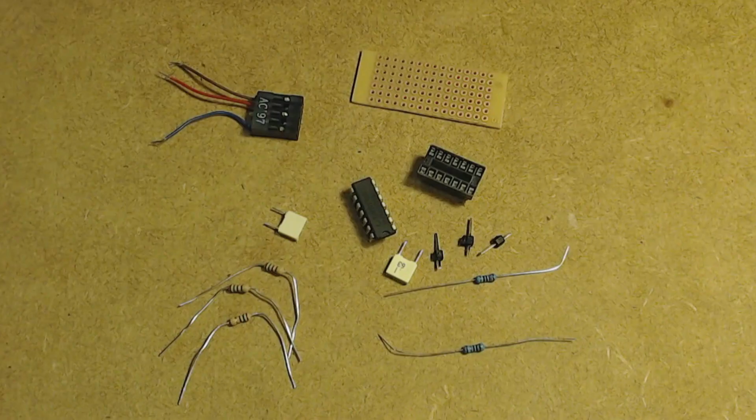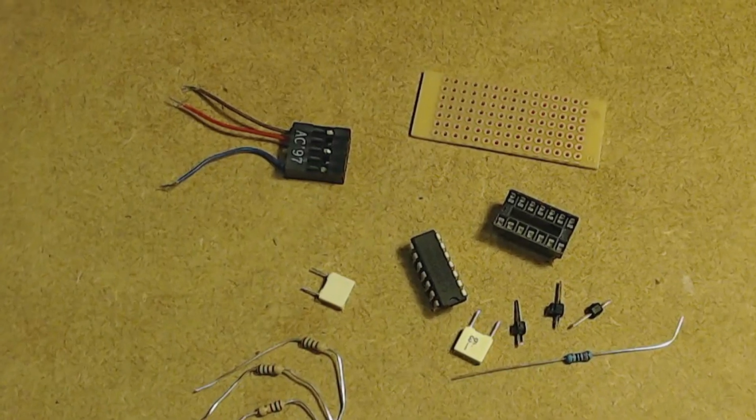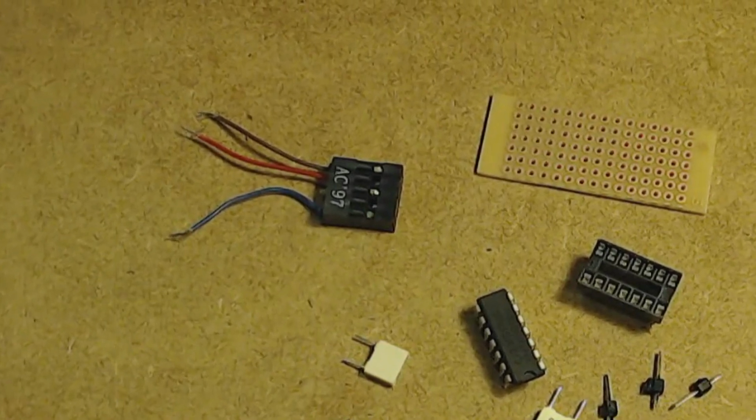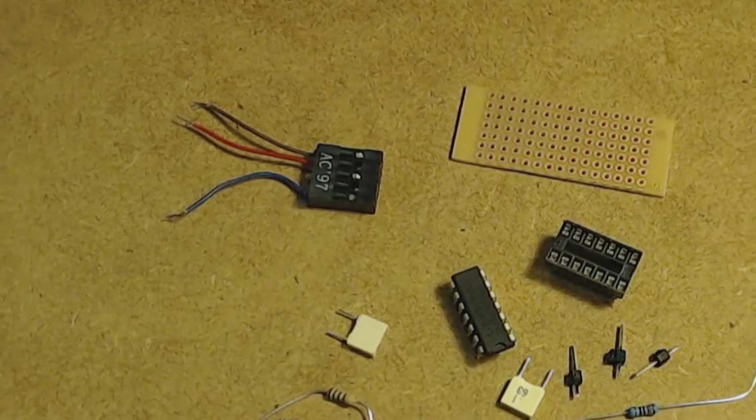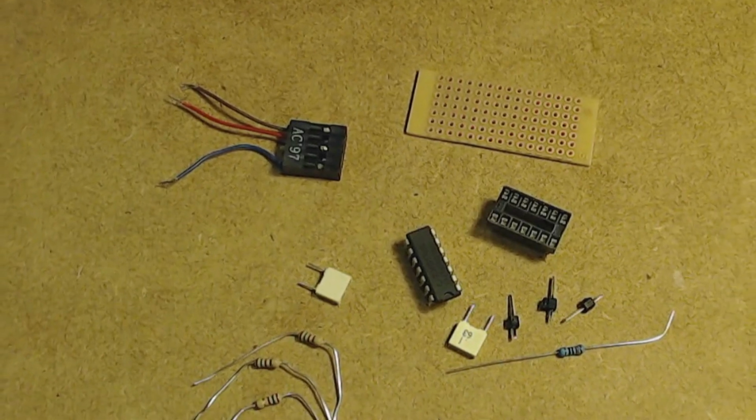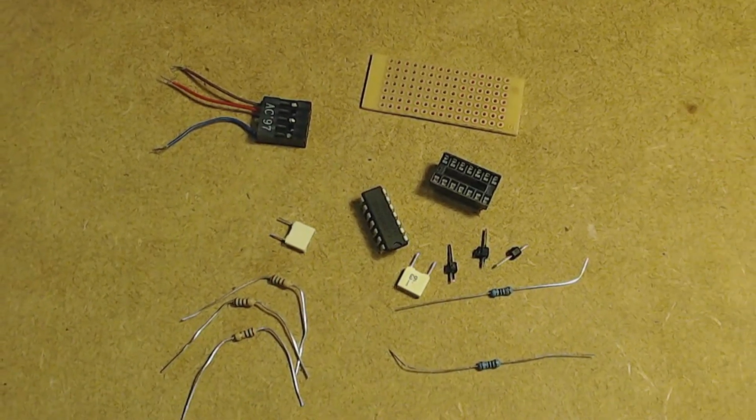I looked into my parts bin and found a small piece of leftover perf board that's just the right size. To conveniently connect to the GPS board, I scavenged this audio motherboard connector from an old PC. It has one usable row of 5 pins, and trimming the cables that I don't need, it ended up like this, with a slightly non-conventional color coding, namely brown for VCC, red for ground and blue for PPS. The other items are the chip, resistors and capacitors needed for the output circuit.